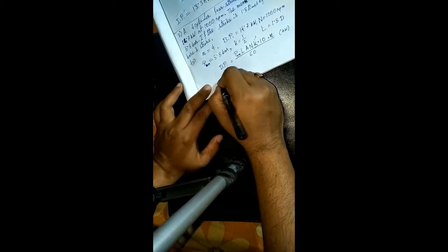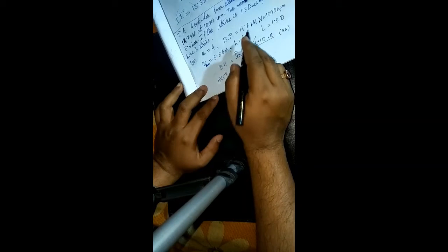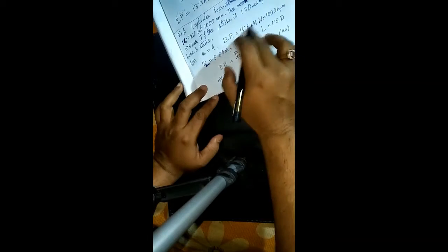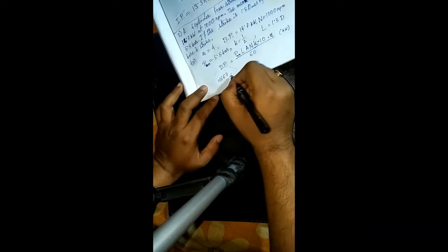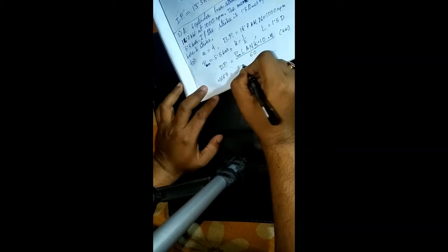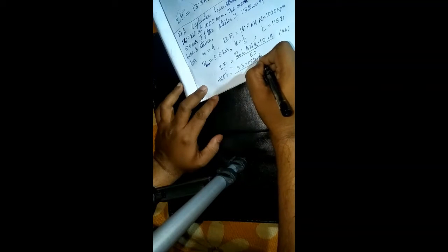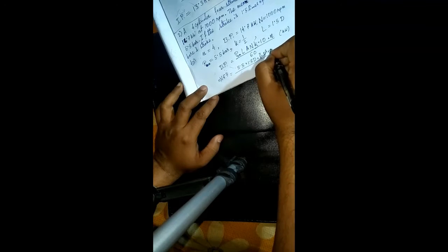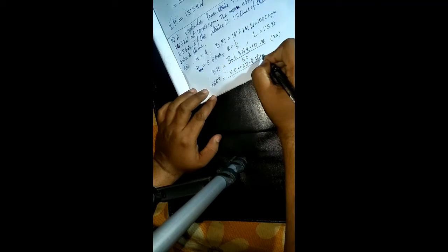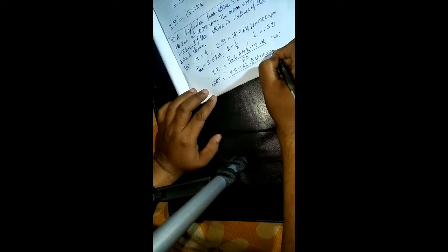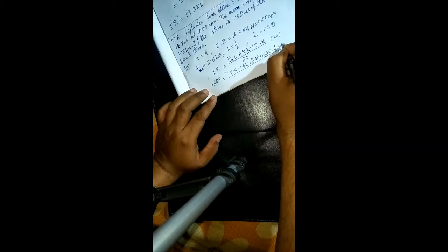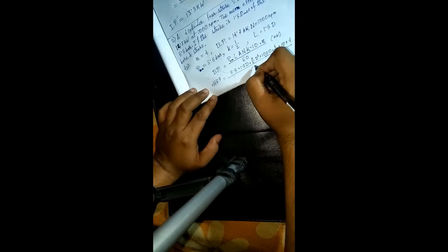So now substituting all these values. Brake power is 14.7 kilowatt. This is already in kilowatt, so we don't need to convert it into watt. Brake mean effective pressure is 5.5. L equals 1.5 D. Area is pi by 4 into D square. Capital N is 1000. The value of K is obviously half for the four-stroke engine, into 10 into number of cylinders 4 divided by 60. So from this relation we can find D.